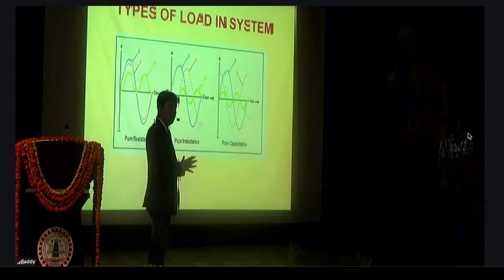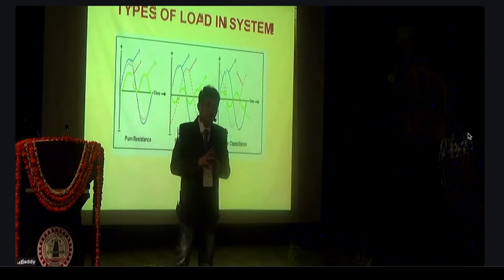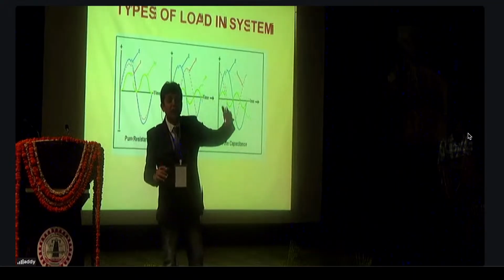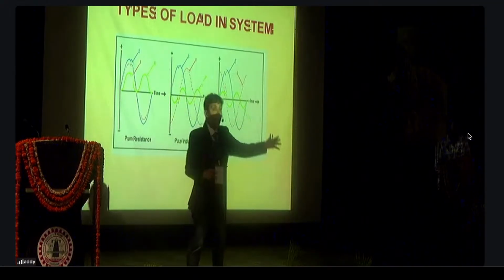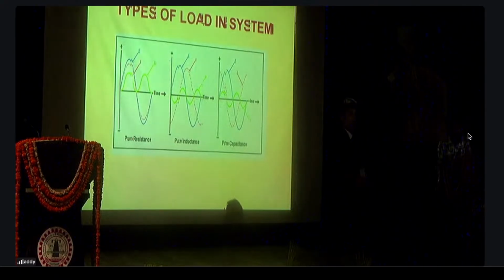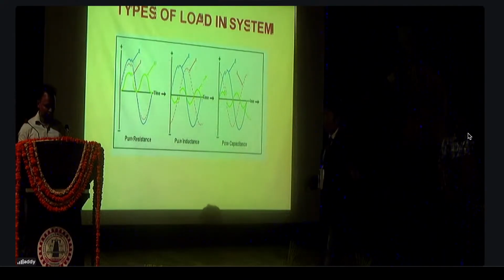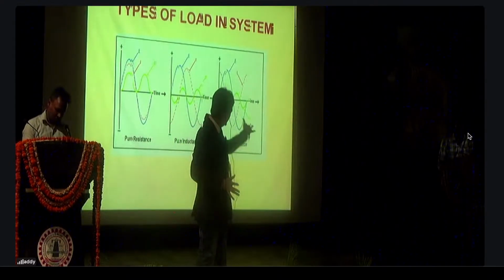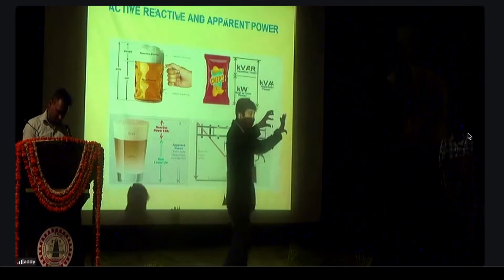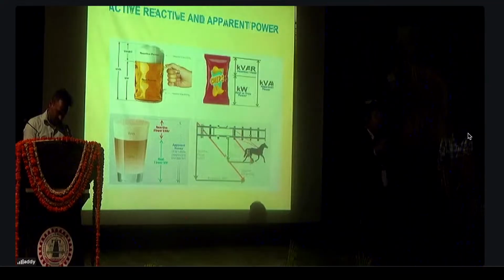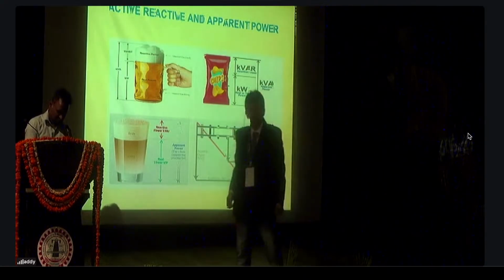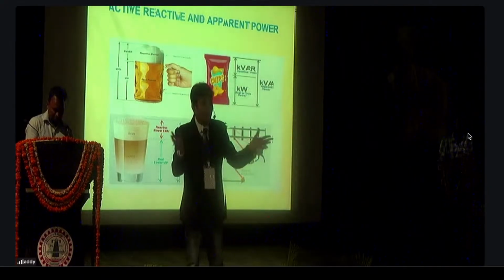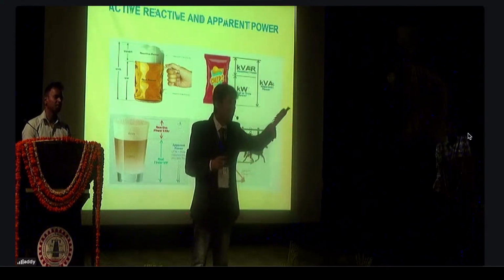Next. Then comes the role of your load. Maybe linear, non-linear, harmonics order, first order, second order, even harmonics, odd harmonics, positive sequence harmonics, negative sequence harmonics, zero sequence harmonics. How they impact your system, you have to understand that thing. You have to understand the role of that kVAR, reactive power. Anyone sitting here can explain the importance of the reactive power for power system. I would be happy to know if anyone can explain that thing. Why reactive power is required?